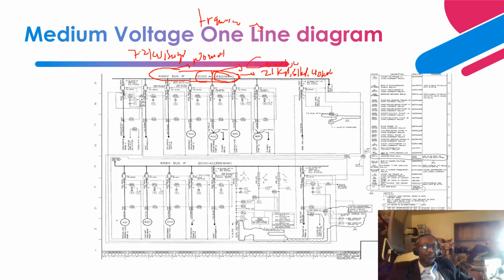The 350 MVA is basically a combination of root 3 times V times I, so your short circuit current times your nominal voltage and root 3. That is how they are able to achieve the 350 MVA. So it's all basically the same. The newer switchgear is basically shown in kiloamps.